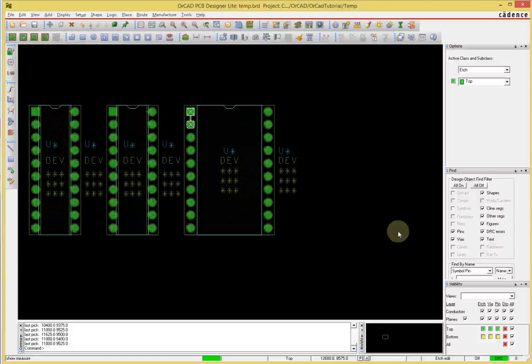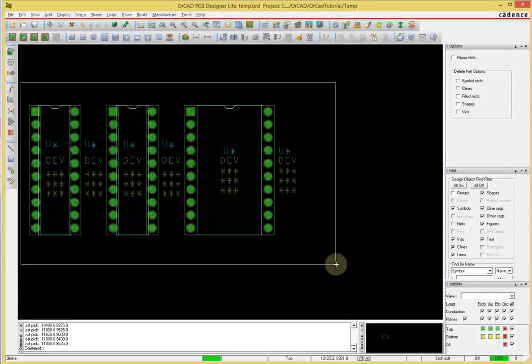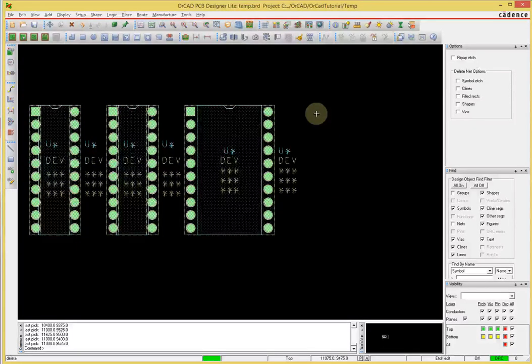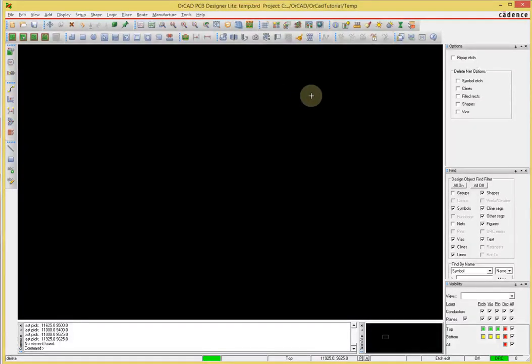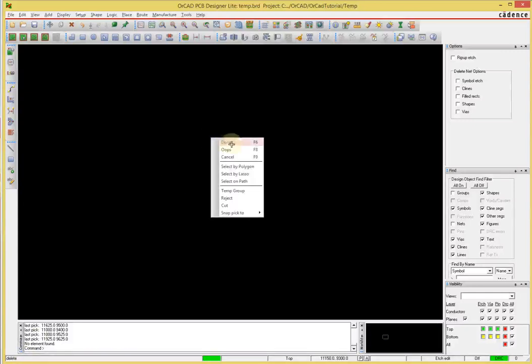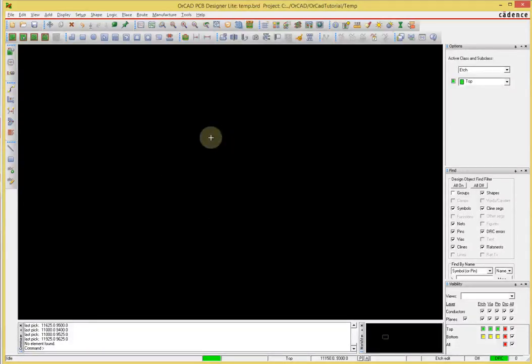Okay. Let's say I want to delete these parts from my window, so I have to first exit the measure mode: right click, done. Notice that it says idle here on the corner. Alright, and I want to delete it, so Control D, and I'm going to select everything, and then I'm just going to click anywhere on the side and it'll go away. My delete mode is still active, so right click, F6 to exit delete mode.